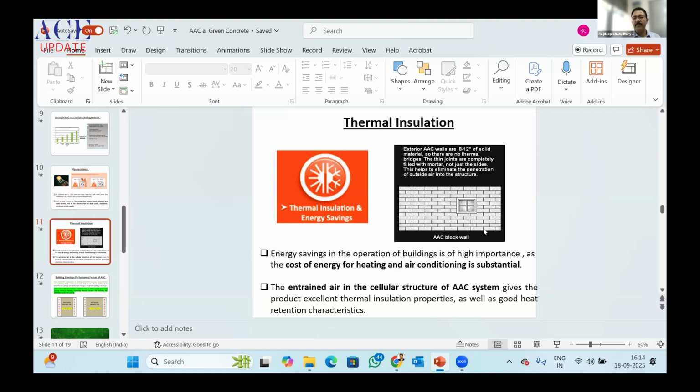And also, why is it happening? Because if you look at the production process, when you're using aluminum oxide as a foaming agent, it's a typical mold. Because of paucity of time, I'm not sharing the production process, but broadly, it's a huge mold. Suppose it's a 6-meter long mold, and you're pouring all your raw material, lime, fly ash, cement, and other products, and then you're adding aluminum powder, then the whole mass pops up like bread.